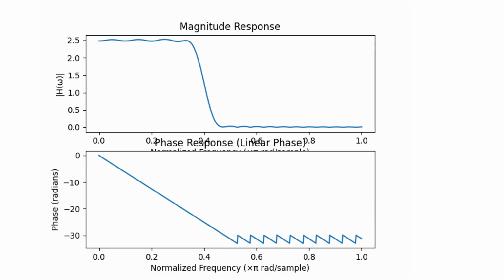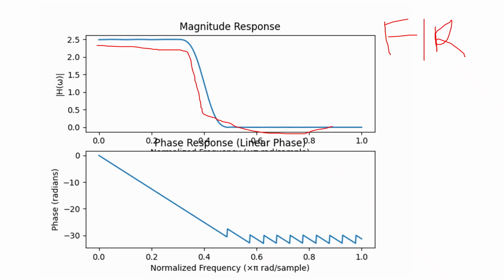The first question that comes while we are talking about this FIR filter is: what is the importance of this window method? Why do we keep on talking about this? The major thing you can understand here is that whenever we design a low pass filter, initially it has multiple ripples. We are trying to design a filter which has a smooth curve. This is our primary target. Here you can see this is a smooth one.